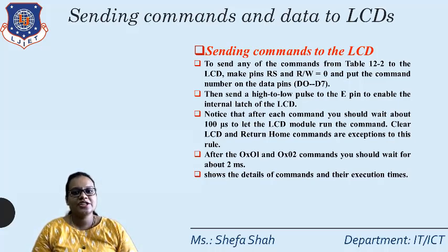Notice that after each command, you should wait about 100 microseconds for the LCD module to run the command. Clear the LCD and return home commands are exceptions to this rule. After the 0x01 and 0x02 commands, you should wait for about 2 milliseconds.